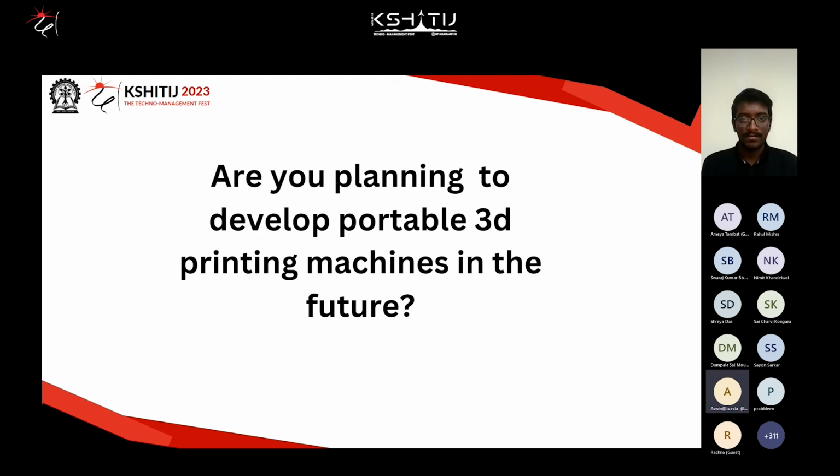Understood. Right now we have a printer in our factory, which is a robotic arm mounted on a crawler, a kind of mobile 3D printer. As I said earlier, we have different printing strategies, like on-site and off-site. I explained this briefly during the presentation. This is on-site printing, where the mobile 3D printer goes to the site and prints the entire structure there. Due to the moving action of the printer, the printable area is multiplied, based on the site area.